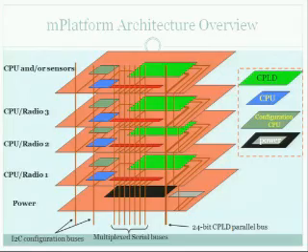Now, in this design paradigm, you can think of a lower-end microprocessor that is continuously on, interfaced to a very small occupancy sensor, like a PIR sensor or an RFID sensor. Whenever this small circuit detects that there is someone in the house, it will automatically enable the voltage regulator, wake up the 32-bit processor with more complex sensing modalities, and be able to do the monitoring. And this is something we can actually do in the context of the mPlatform.